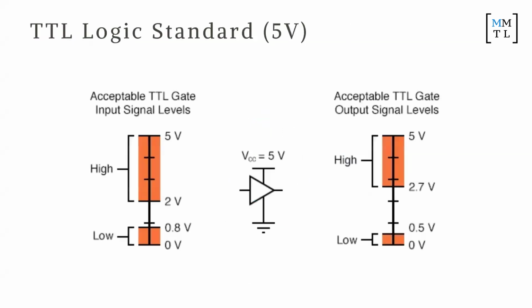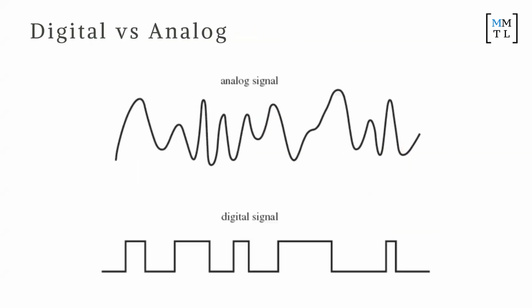So let's go back. So what I'm trying to say is I want, for example, an average value of 2.5, right? So something in between 5 and 0, with a digital signal. So a signal where we are only locked into ones and zeros. Any thoughts on how we can achieve that? Yeah. Resistors and stuff. Resistance is one. No, resistance is not quite it. How would you achieve, for example, so I say I want an analog signal that averages at 2.5 volts. Okay. How would I achieve it if I'm only allowed to do 5 and 0? Yeah, the equal number of 0 and 5.